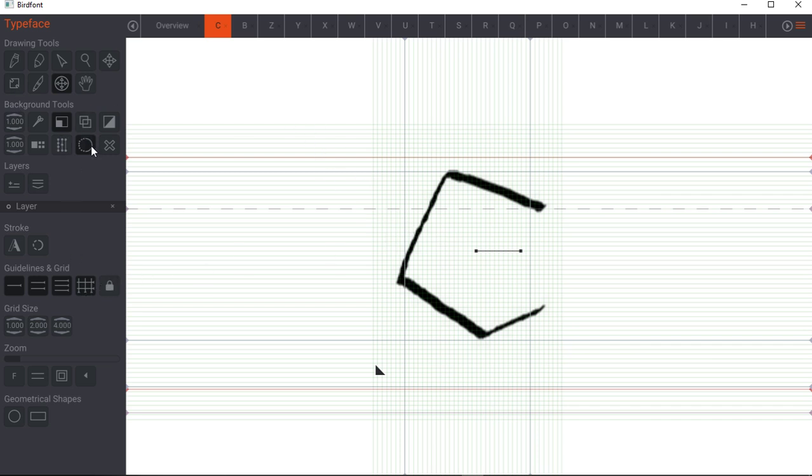Let me try to auto trace it. So the auto trace right here is in the background tools again, this little circle icon next to the X. You click it, and then it takes a little while, and then it will update and trace the whole entire thing, placing Bezier curves across the whole entire image for what that sector needs to show. So there it is, it's done. It looks a little darker. That's how you can tell that it's done.